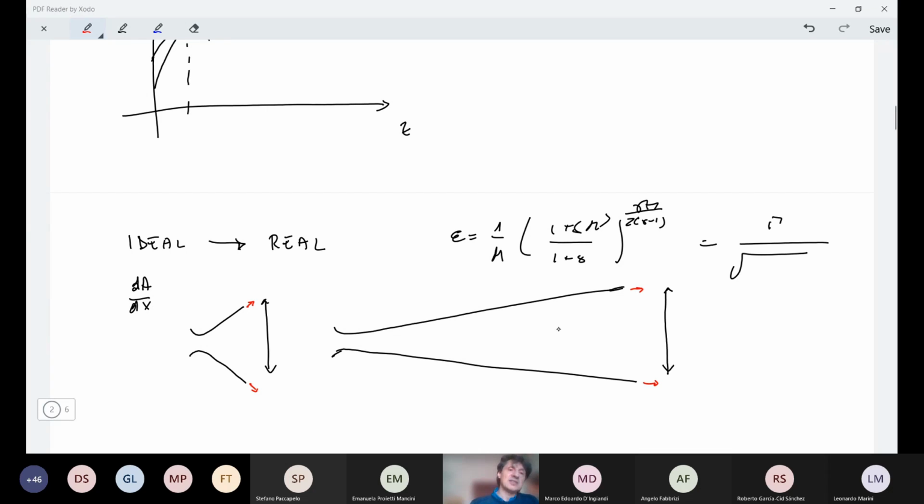So you see that here the exit flow is less one-dimensional, and less one-dimensional means that we also have to consider components of velocity in the radial direction. Even if we have azimuthal symmetry, so we can consider axisymmetric flow, in principle the larger the diverging angle, the higher will be the radial component of velocity at the exit of the engine.